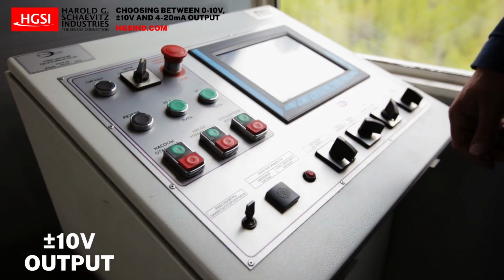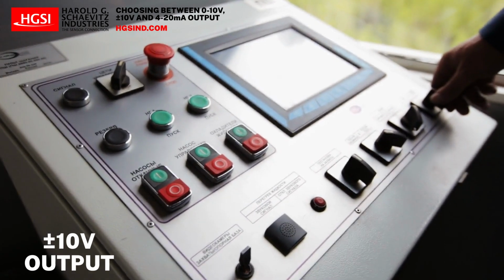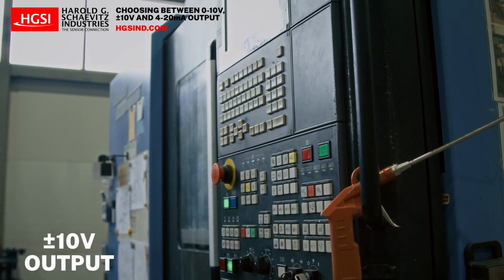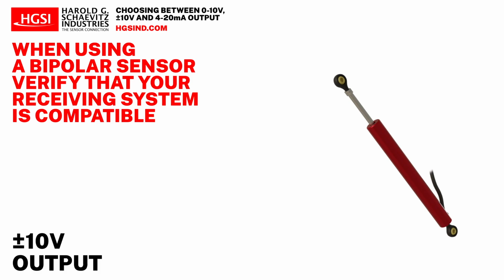However, it's important to understand that not all control systems support bipolar inputs. While plus or minus 10 volts is common in motion control and higher-end systems, many general-purpose PLC inputs are designed for unipolar signals like 0 to 10 volts or 4 to 20 milliamps. So when using a plus or minus 10 volt sensor, it's important to verify that your receiving system is compatible.